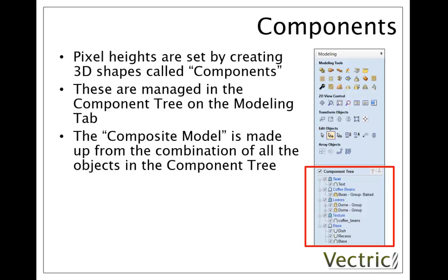The result of all these components and the combine mode, so how they're interacting with each other, is what gives us that finished part, and that's what we're going to machine when we go ahead and use 3D toolpaths like the roughing and finishing.